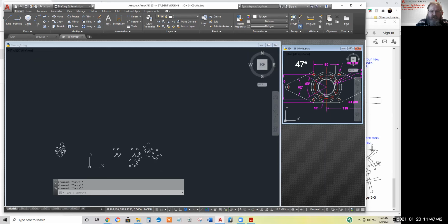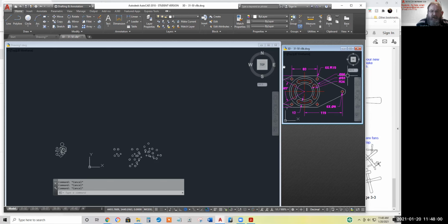You know, the small one, the large one, and the red center line one. The small one is diameter of 50, the red one is radius of 36. Probably should have dimensioned that by diameter. And the outer object line is a diameter of 96.